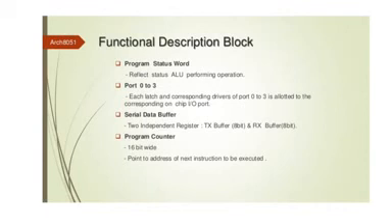Next, after parity, at the D2 bit you have the overflow flag. This is for when you are carrying out your multiplication. The overflow flag is set if there is a carry from the 7th bit but not from the 6th bit, or there is a carry from the 6th bit but not from the 7th bit, otherwise it is cleared. What I meant to say here is that the overflow flag is set whenever you have a carry from the 7th bit or the 6th bit.